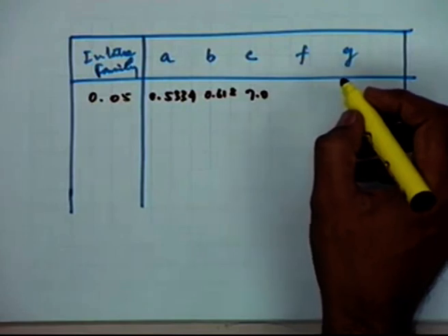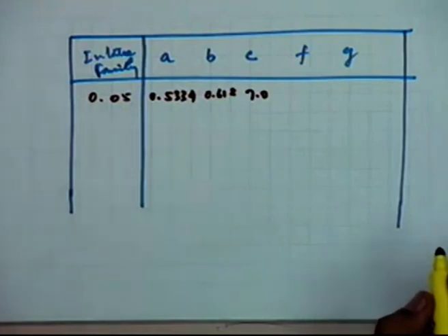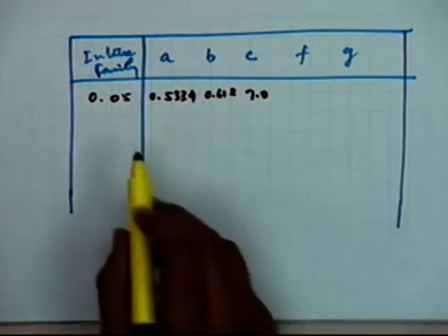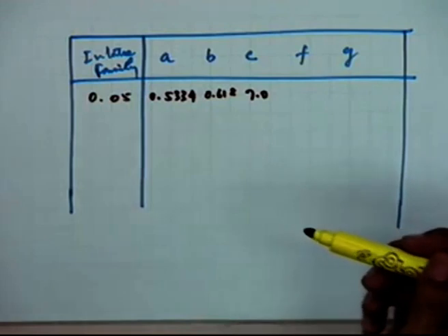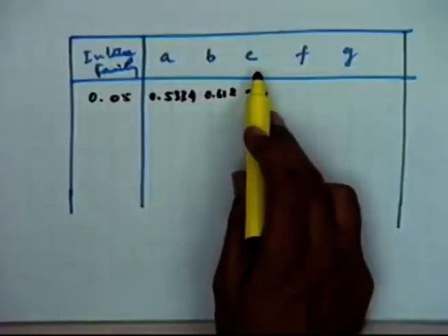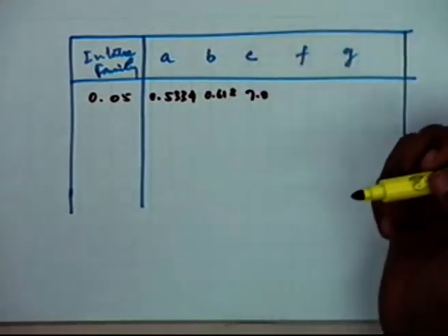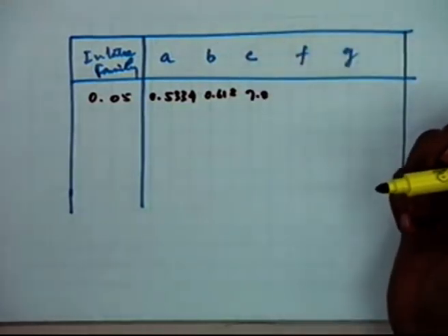In some cases, if the soil characteristics are such that you are not able to represent the soil through a single parameter, if there are two curvatures of the soil infiltration capacity curve, then this C parameter is helpful, but in this particular case all the family curves have the same C value.